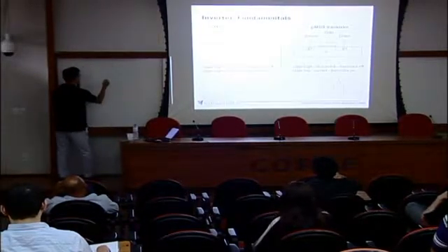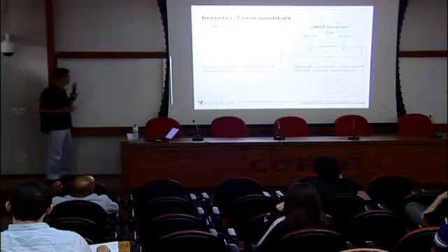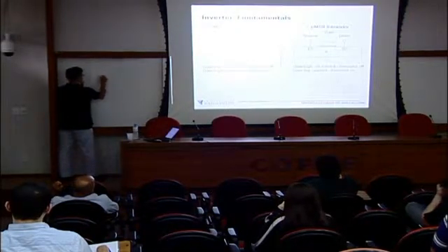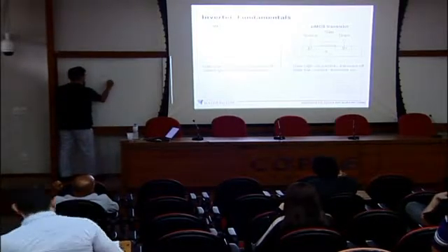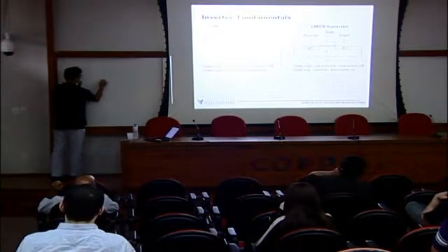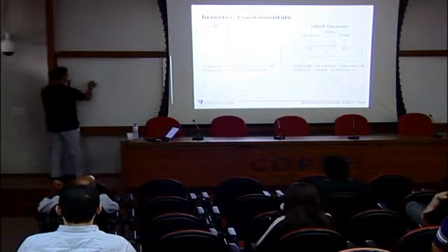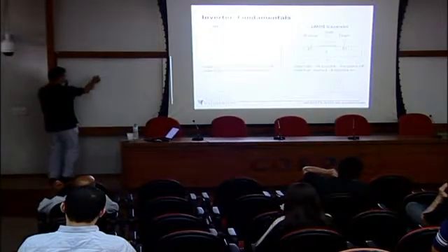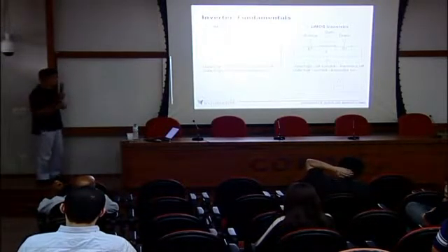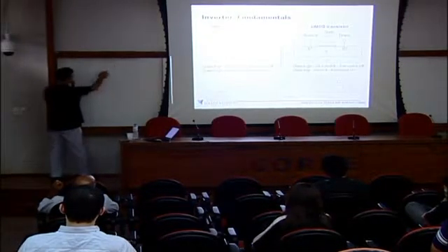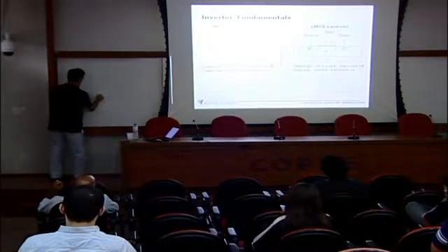So if we apply, for instance, 0 in there, okay? If 0 means it's a negative, then that means positive force will be attracted more toward this region. Then this one will be more positive, I would say it's a P plus. And then this source is still negative. Then the energy barrier, the depletion zone, will be increased, right? Then there is no current. So when we apply 0 on the gate, then we will get a 0, right?